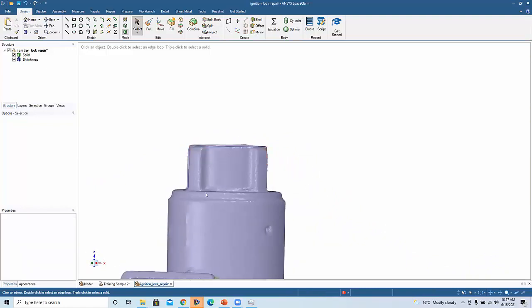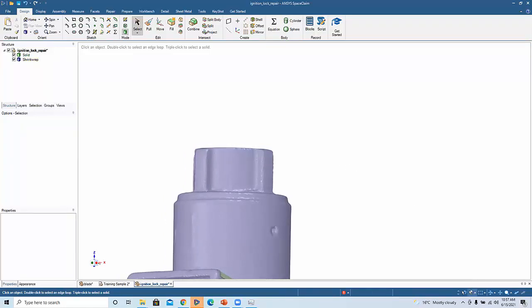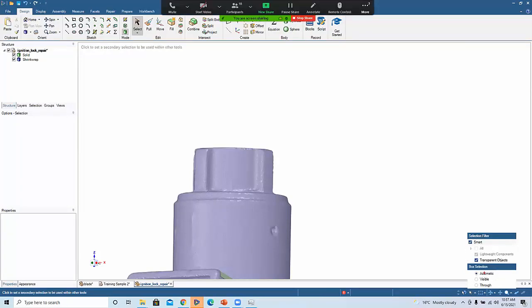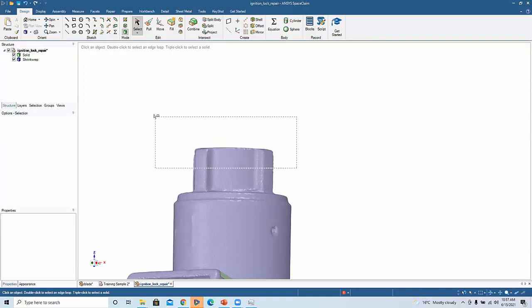So say I want to move this boss up to a higher height. What I can do is go over here in the selection filter. In the selection filter, you'll see there's box selection, but there's automatic, visible, and true. What I actually want right now is to click on True. Oftentimes when I'm doing mesh manipulation, I'll turn my selection to True as opposed to automatic or visible, because I want to select this entire box on the top.